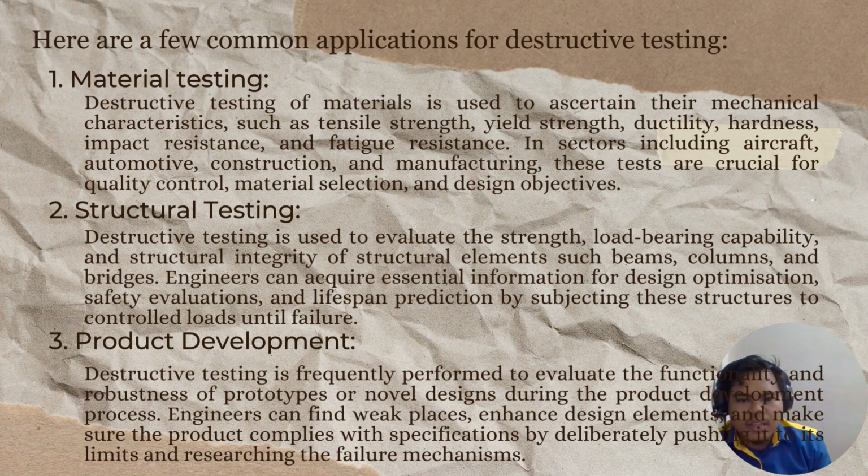The destructive test is used to evaluate the strength, load-bearing capacity, and structural integrity of structural elements such as beams, columns, and bricks. Engineers can accurately establish information for design, optimization, safety evaluation, and lifespan prediction by subjecting the structure to controlled load until failure.